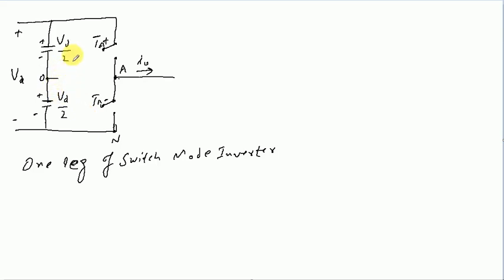Now there is one more thing that you are already familiar with if you have seen the recorded lecture, in which we discussed that if we have only a resistive load, then of course we don't need anything in parallel across these switches. However, in most practical applications we find the load to be inductive, just as we saw in the example a while ago. So we need some provision for the current flow when the current changes its direction and is different from the output voltage.